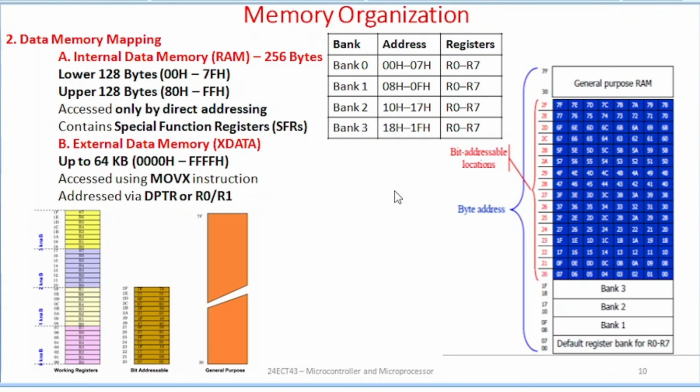The data memory access space consists of an internal and external space. External memory can be accessed with the help of the MOVX instruction using DPTR. These on-chip data memory locations are 128 or 256 bytes, with the total size of data memory expandable up to 64 KB in external RAM devices.